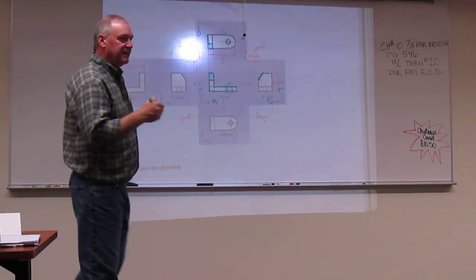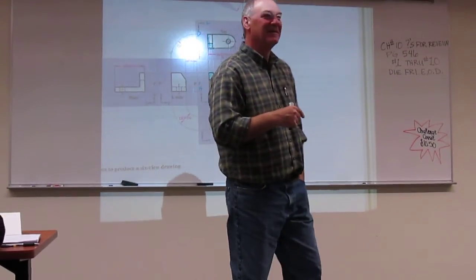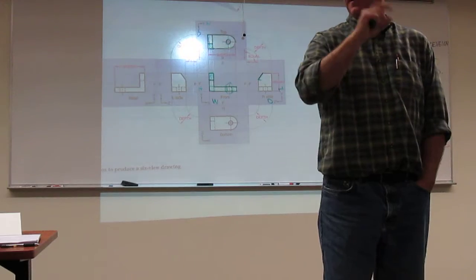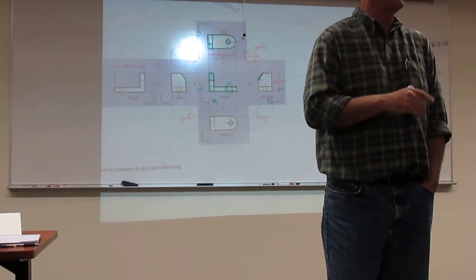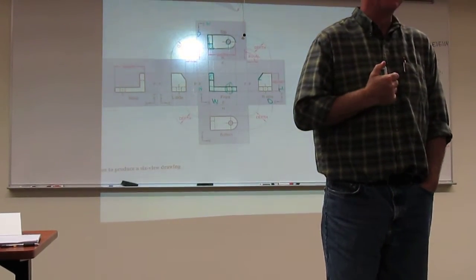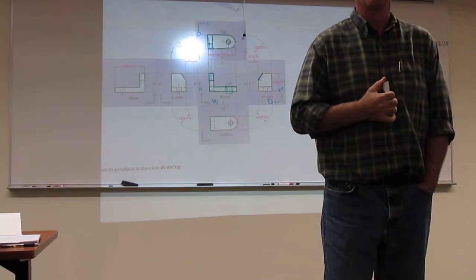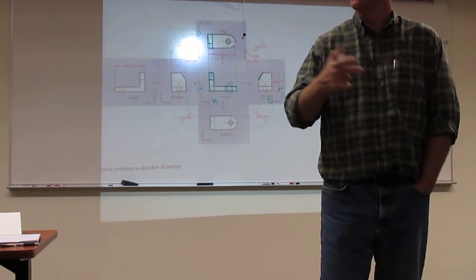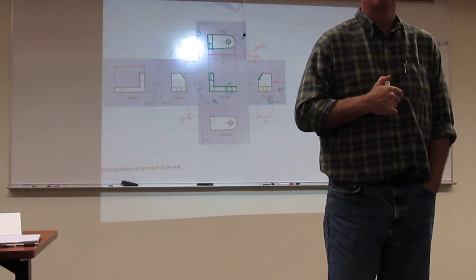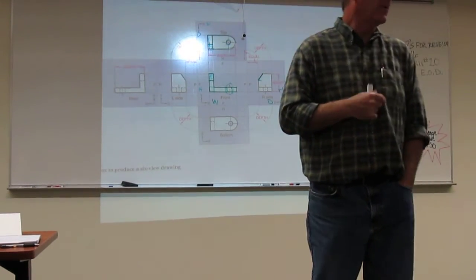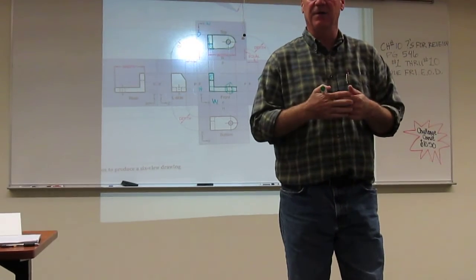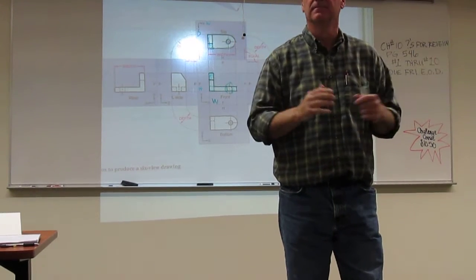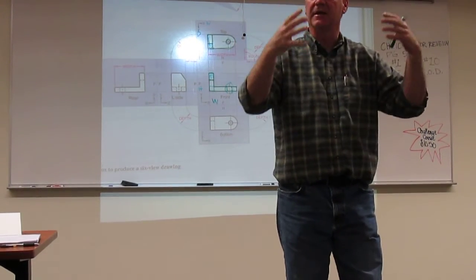You'll have a key to this and know when it occurs a little bit later also. Once we put dimensioning in, you'll draw an object and you get ready to print it and you notice one object has no dimensions on it. It's probably not needed. That's just a fact, because we dimension the same way we draw. And that's a big key. Right now, what you need to do is look at every piece of geometry. Generally, it takes 2 views to describe any feature. And then you just look at how I'm going to get them.